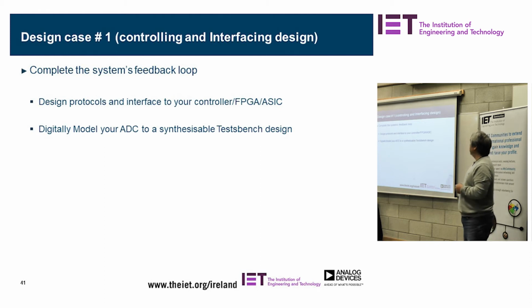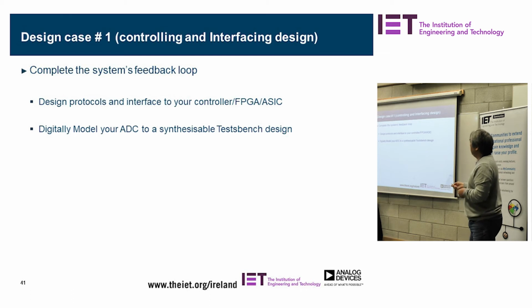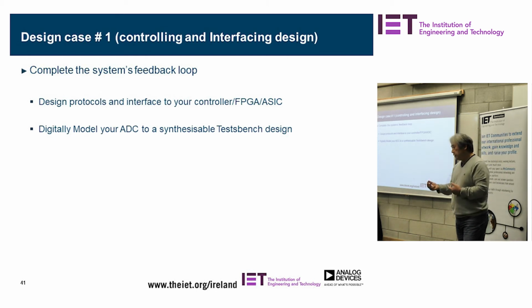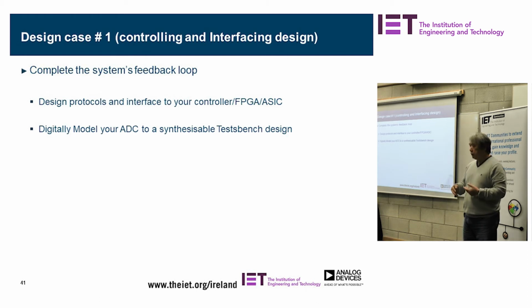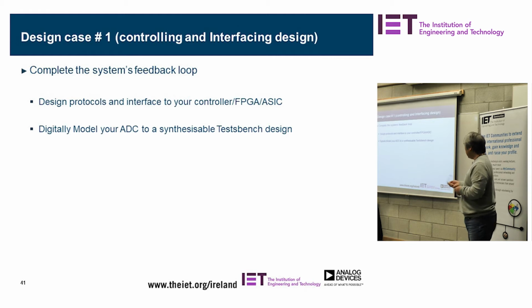Okay, so we look at one of the design cases, control interfaces. We look at the protocol interface and how you control it through the FPGA or ASIC or even the microcontroller. I use the ASIC because I don't want to use other people's compilers. It's easier and faster. I have my own tools, so I get it done quicker that way. But people can do the same thing with a microcontroller. And we look at some of the models, how you synthesize your ADC from a model from a test bench design.